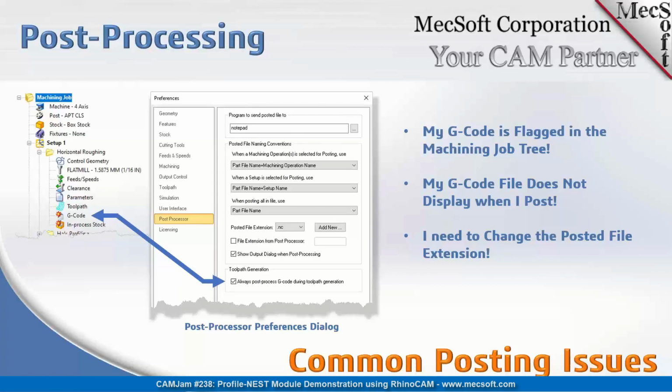You can set it to another editor. If you have a G code editor that you're using, you can select this three-dot button, go ahead and locate your executable file for your post editor, and it'll show up in this field right here. And that's the dialog that will pop up whenever you post G code. So if you don't see your G code automatically pop up, check this field up here, make sure that at least it's pointing to Notepad, so it'll pop up in Notepad.